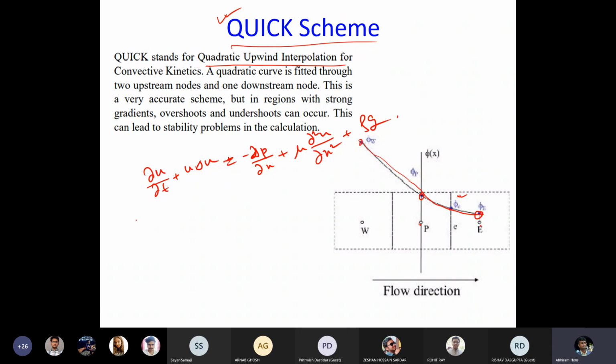So you have an unsteady term, this is a convective term, and due to this the whole system becomes nonlinear, right? And this is the pressure term, this is your viscous or diffusive term, and this is the body force. Okay, so we intentionally started with a heat transfer problem. We have not yet touched it, because this is a nonlinear partial differential equation and it is not also